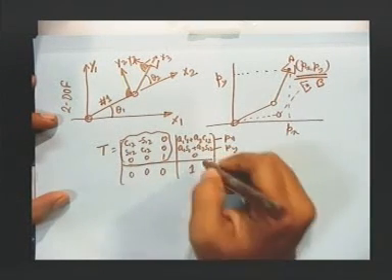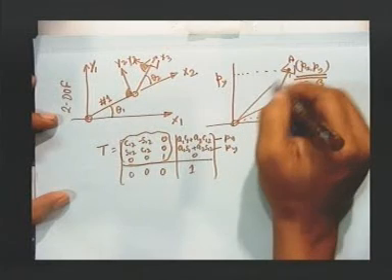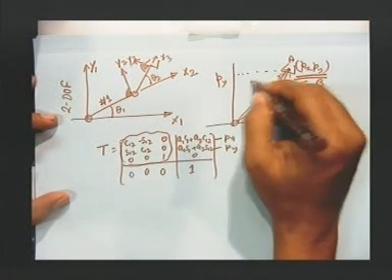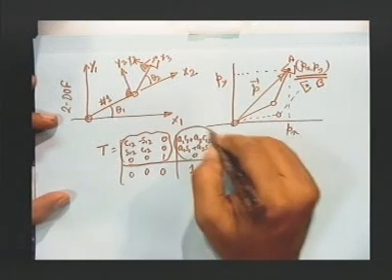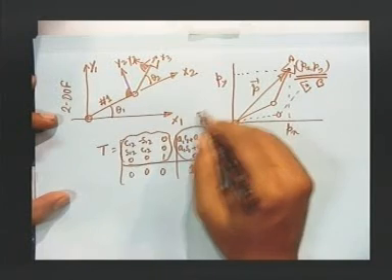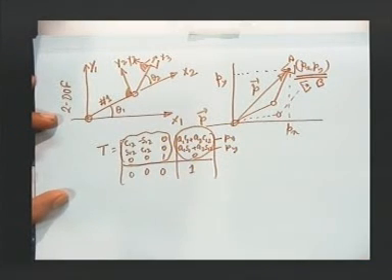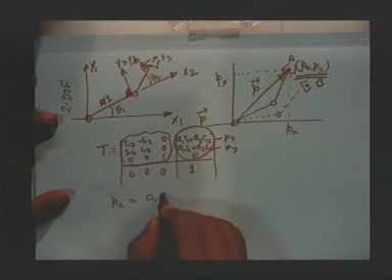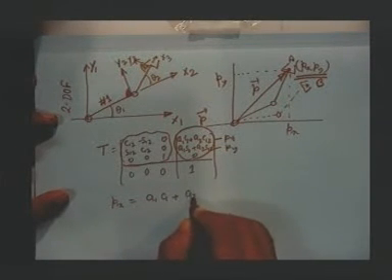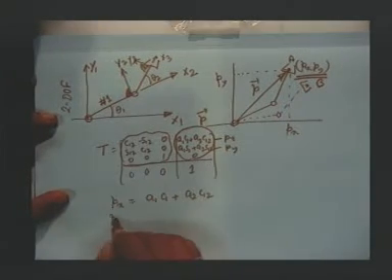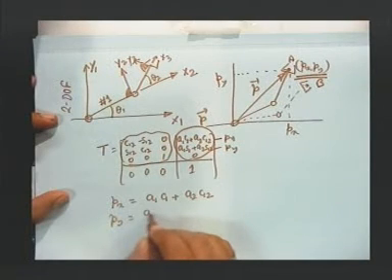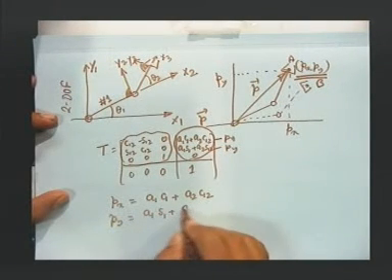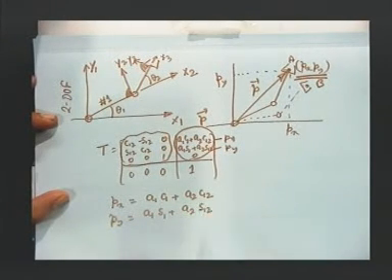So, this corresponds to this vector p. This is a p vector whose components are p x, p y. So, let me write p x is equal to a 1 cos theta 1 plus a 2 cos theta 1 2, p y is equal to a 1 sin theta 1 plus a 2 sin theta 1 2.